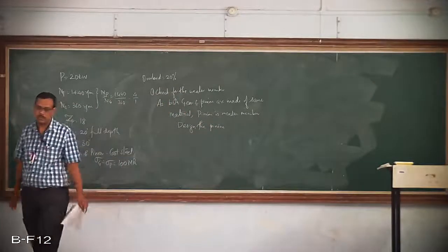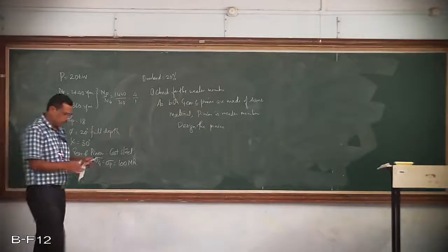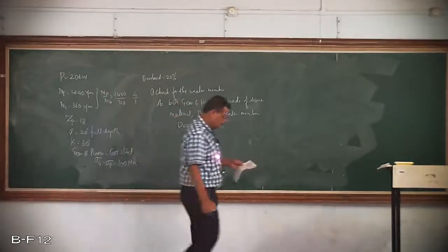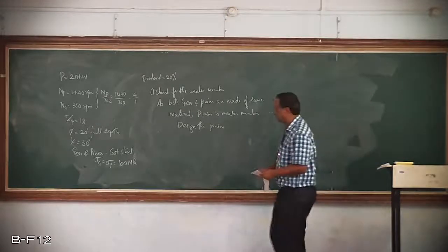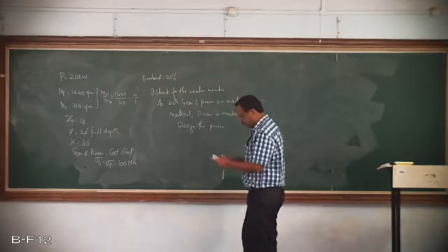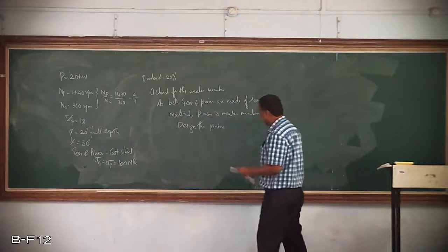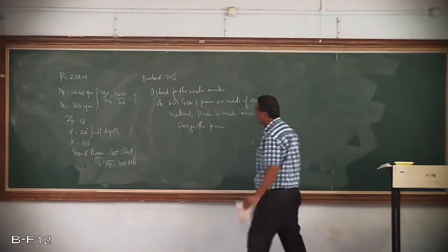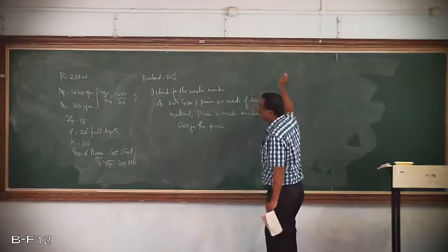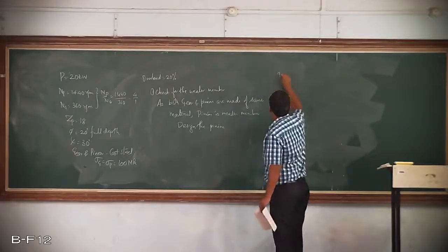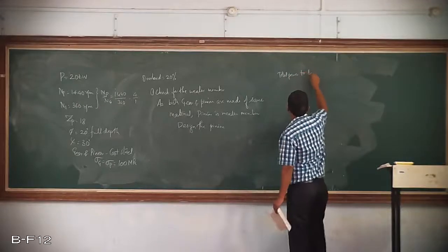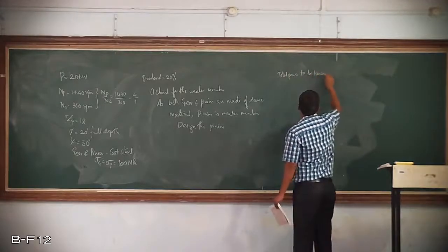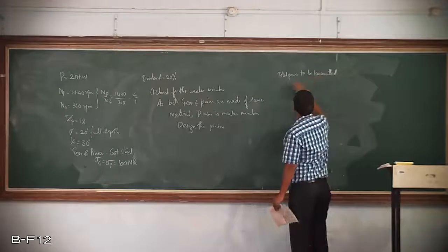Second, we need to now find out the velocity and thereby the tangential loads. Therefore, first we will calculate, anyway we have to go with the pinion, the power transmitting capacity with 20% overload. Total power to be transmitted, considering overload.